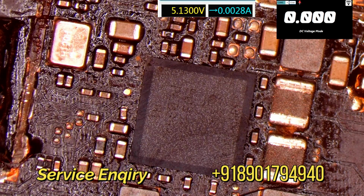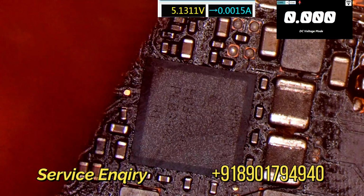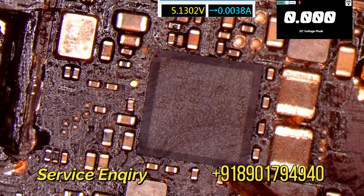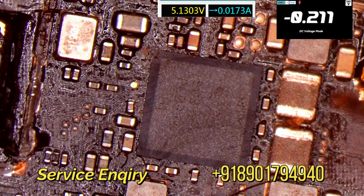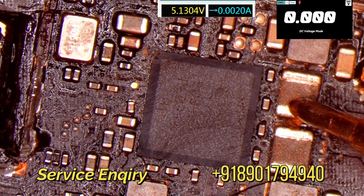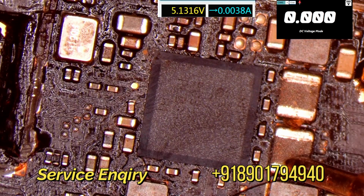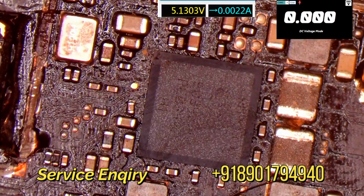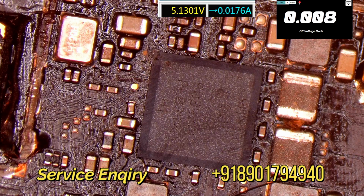The requirement is here, but it is less, right? There is a shorting, so the power drops, the consumption, right? So the power IC does not enable, I mean to say does not activate, right? Look at this, 2.1, 2.2. Now look at the buck, no buck voltage, because the power IC does not produce the buck voltages. Because the power IC does not activate, the requirement is not fulfilled. If the power IC requirement is fulfilled, then the power IC produces the voltages, right?